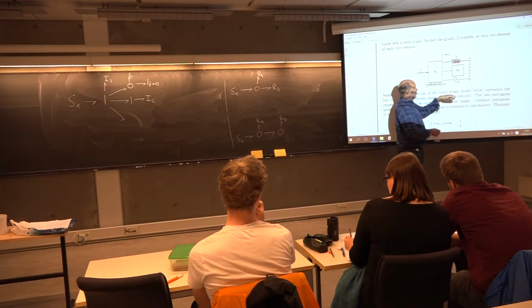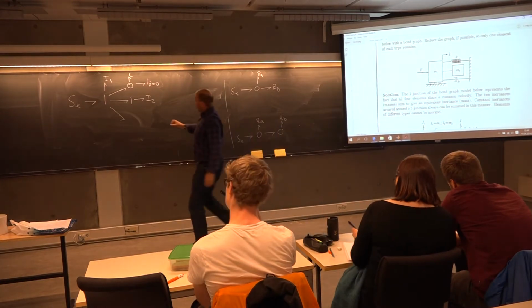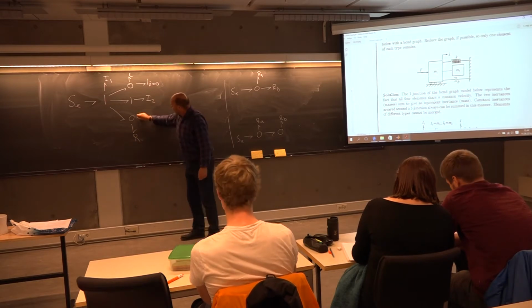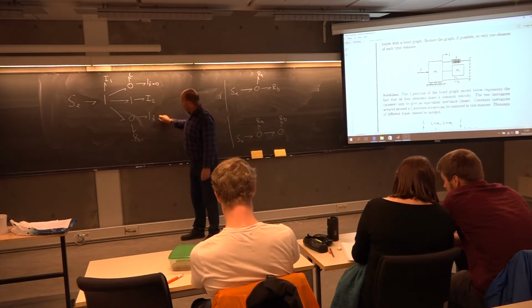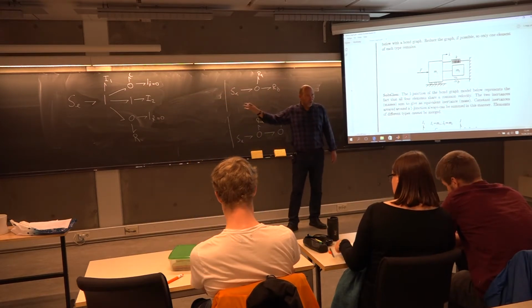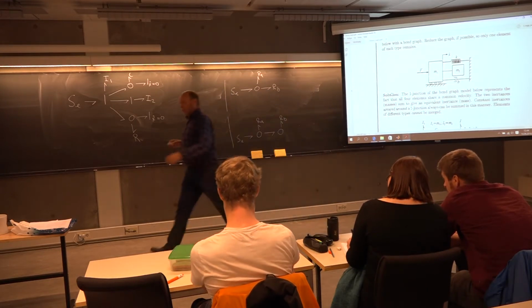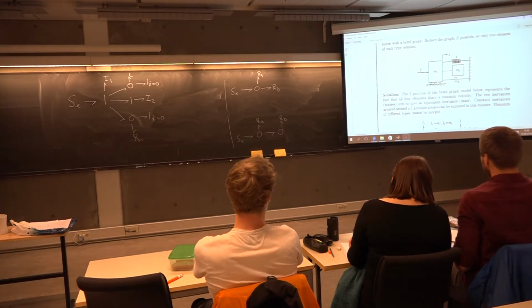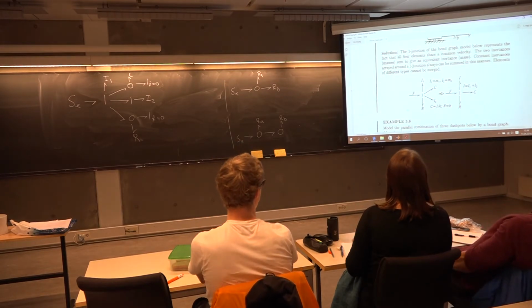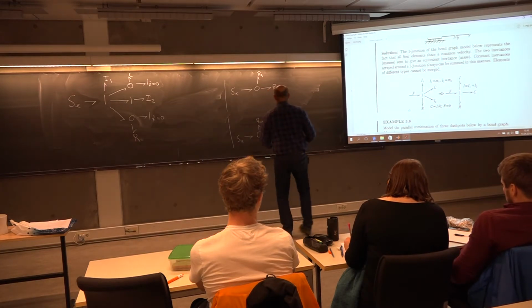Same now with the damper B down here. Same force on each side. Then we insert it using a zero junction down to a resistance. And then we continue, hitting a solid wall, which is not moving. This will be what we call the raw bond graph for this example. I'm not sure if the book has done it so thoroughly. No, it cheats a little bit. Goes a little too fast. Let's see if we can get there.